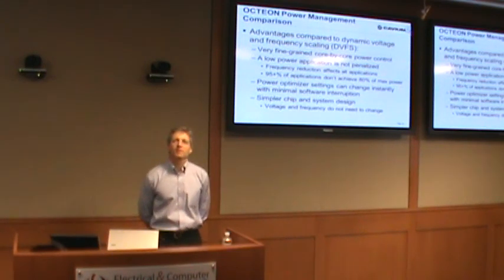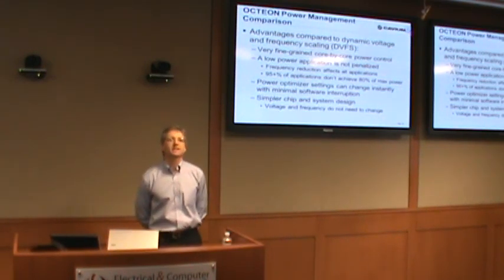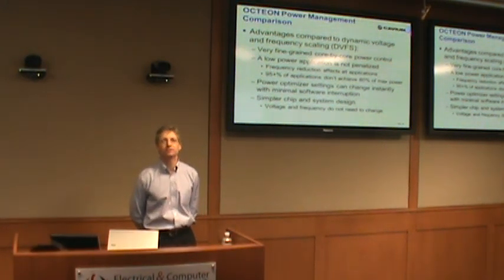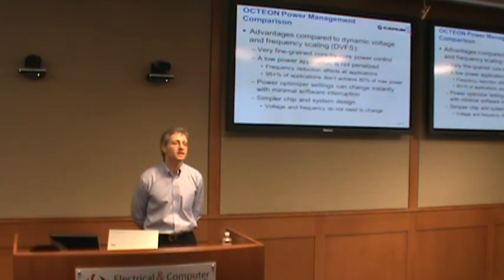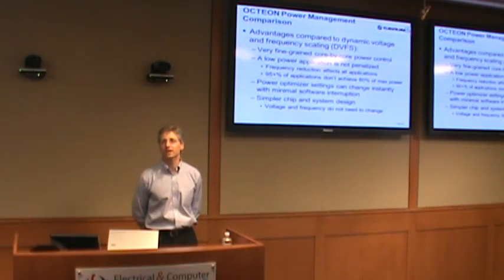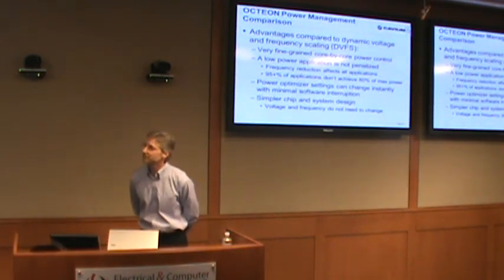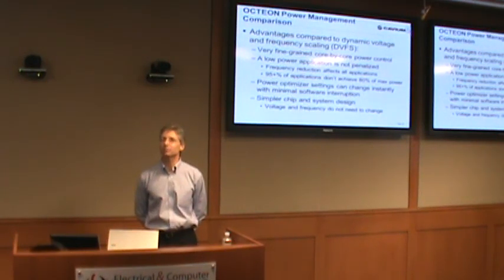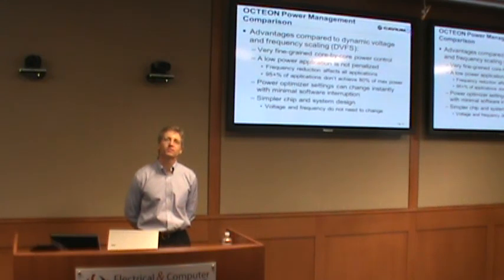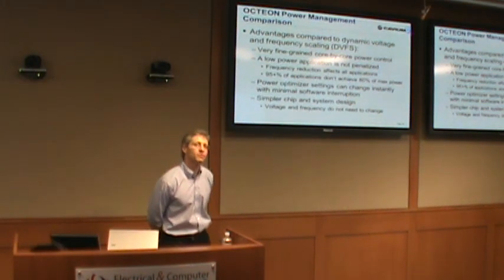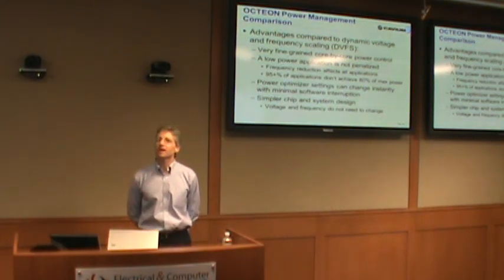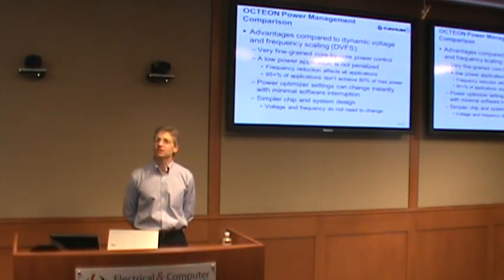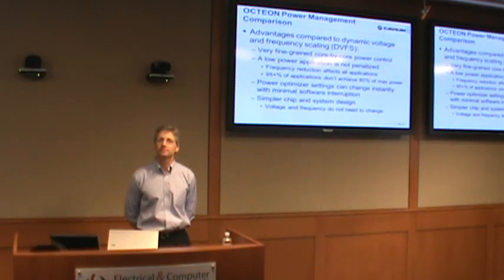So there are a lot of pluses and minuses, but some nice things about this technique compared to the very common dynamic voltage and frequency scaling out there is that with this technique you can have very fine-grained core-by-core power control. A low-power application is not penalized. For example, if you reduce power by reducing frequency, that slows down every application, not just those that are consuming a lot of power.